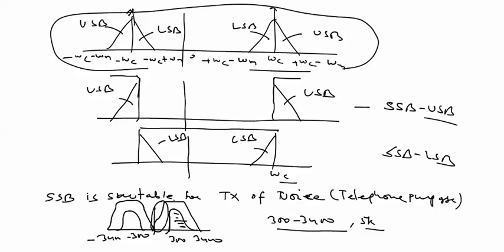But the actual audio range is 20 Hz to 20 kilohertz. There is no initial spectral gap, or a very negligible one, so the filter method is not useful for this audio baseband signal. In video also, there is no spectral gap from 0 to 4.5 megahertz, so SSB is not useful for video. SSB generation via the filter method is useful only for the voice signal, the telephony case. In the remaining cases, SSB via the filter method is not useful.